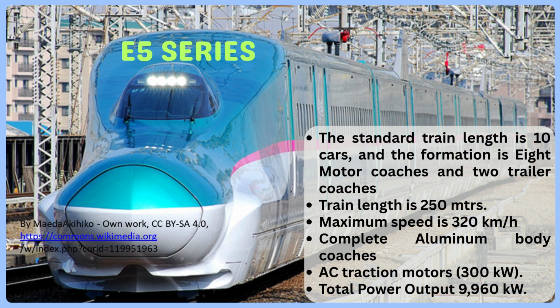The total power output is 9,960 kilowatts. Single-phase overhead supply is interfaced to the traction motors with power converters. Traction transformers and traction motors represent the high power systems based on electromagnetics. Advanced design for electromagnetic and electromechanical power transfer, materials, and cooling are the key design aspects.